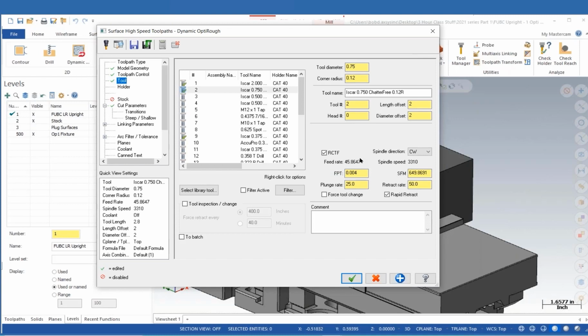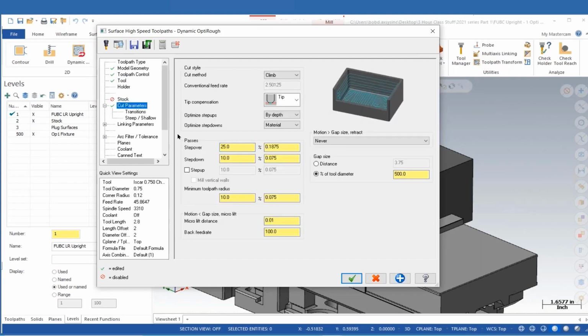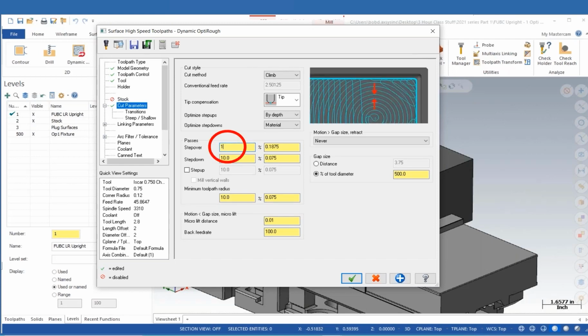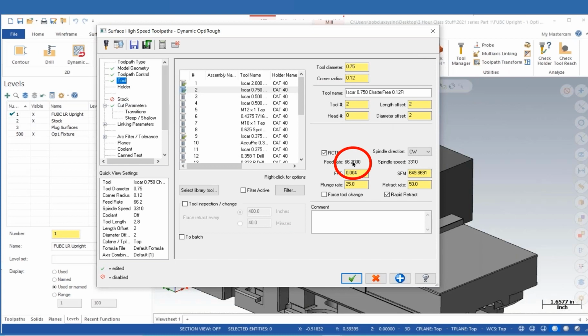It can't get evacuated in the chip anymore. There's only two other places it can go, either my cutter or my part, neither one of which is optimum. So I increase the feed rate, which is in turn going to increase the chip thickness and give that heat someplace to go. And again, the smaller this value, the larger that value. Just a brief discussion on that.